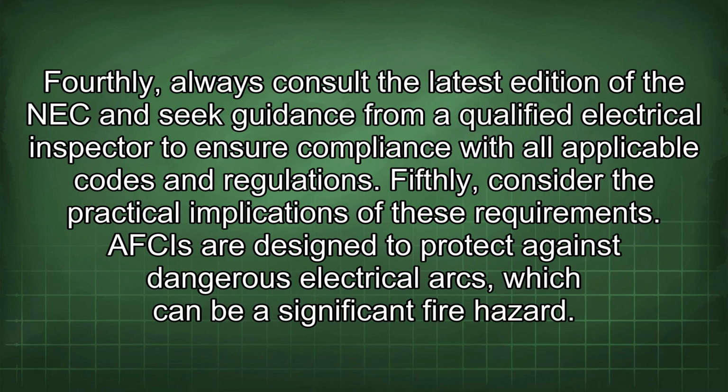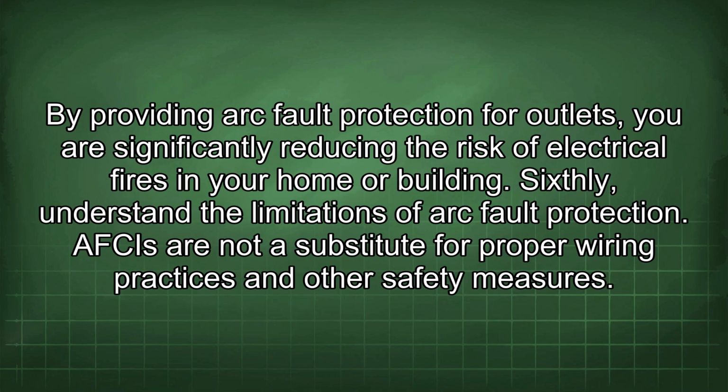Fourthly, always consult the latest edition of the NEC and seek guidance from a qualified electrical inspector to ensure compliance with all applicable codes and regulations. Fifthly, consider the practical implications of these requirements. AFCIs are designed to protect against dangerous electrical arcs, which can be a significant fire hazard. By providing arc fault protection for outlets, you are significantly reducing the risk of electrical fires in your home or building.